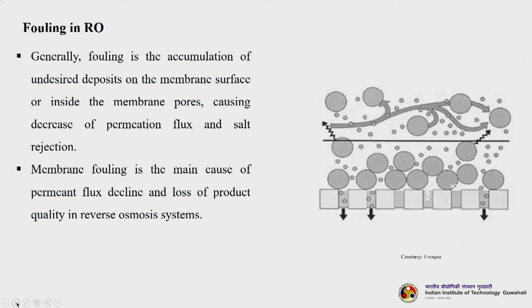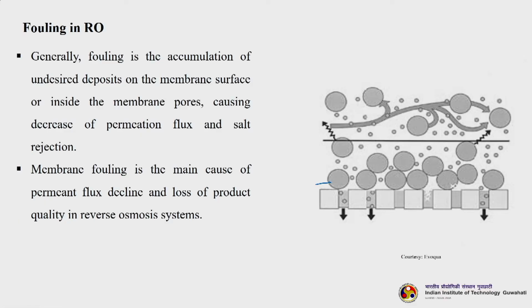So, let us now understand fouling. We have discussed fouling during microfiltration and all. The same process applies to how the fouling occurs. Initially, the concentration polarization will occur. That means the buildup of these solid molecules; you can see different size molecules getting deposited on the surface of the membrane. Some solutes will block the pore mouth. You can see they are blocking it partially here, and some solutes which are smaller in size than the pore mouth eventually get inside the pores, and the passage is constricted.